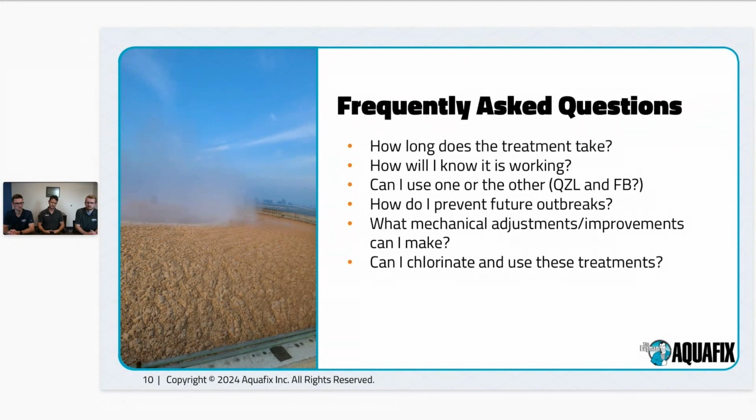Mechanical adjustments can also include just keeping it out of your system, headworks type stuff. Grease traps. Yeah, making sure your community's grease traps are working correctly. Obviously, we know a lot of operators' relationships with business owners can be not the closest. They don't communicate that great, but that would truly help.